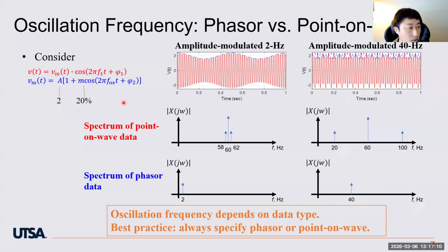And the 60 Hertz waveforms, shown as the red curves in the two plots on the top, are kind of boring. What is interesting is the variations in their magnitude and in their phase. So that's why we condense all that information into phasors and only communicate the phasor information to the control center.